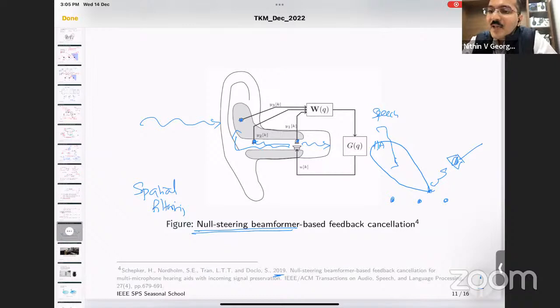In this problem, I have a microphone array where we are trying to pick signal from the environment. Suppose all of you start speaking, but I want to listen to only one person. Can I do that? Yes, because my array can be told to pick sound only from one person and ignore everybody else. So I should create a beam in the direction of that person I want to listen to, and create nulls in the direction of other people who are creating noise.